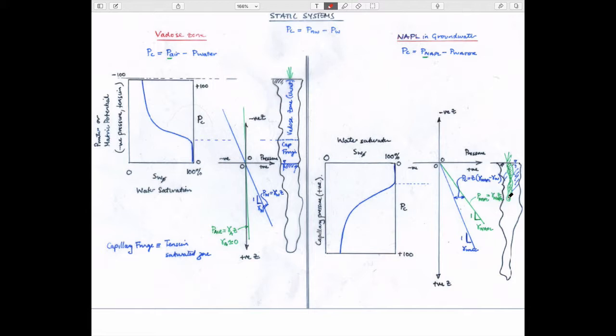So what we can do is we can think of these again as a swimming pool. The porous medium doesn't make much difference. We could think of it as a test tube, a swimming pool of the blue fluid, a swimming pool of the green fluid, and calculate what the pressure distribution would be in going from the surface to depth in the swimming pool. If it's in water, we know that the pressure here at the surface is atmospheric. Gauge pressure is 0.